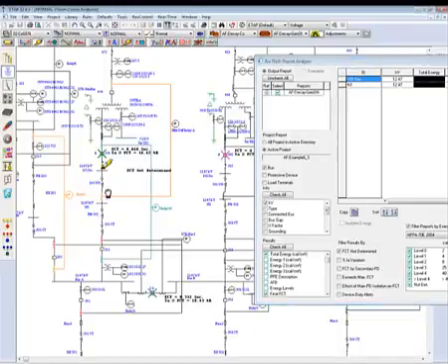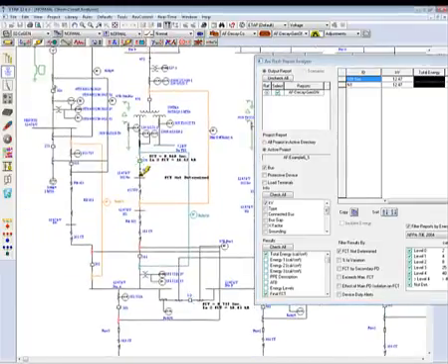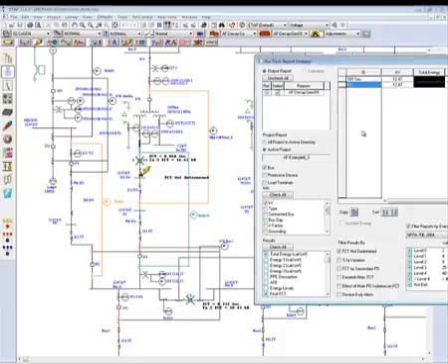Notice that the branch that the generator is feeding is not being de-energized. In ETAP, the generator will be sustained at steady state, and it's required for it to be de-energized in order to fully find the fault clearing time. You can also see and inspect that there's only differential set up and no overcurrent device here in this first level to de-energize it. Similarly, N1 is the same case, so we can launch this viewer.